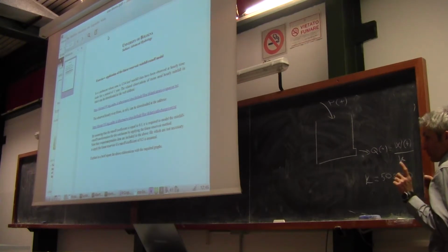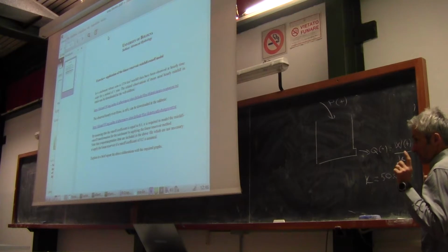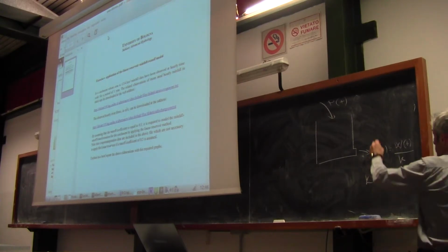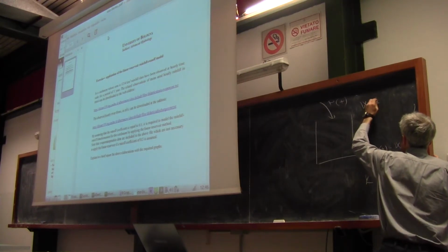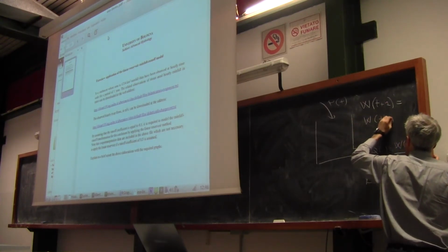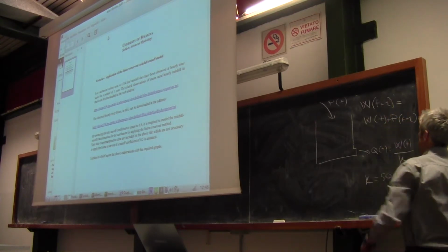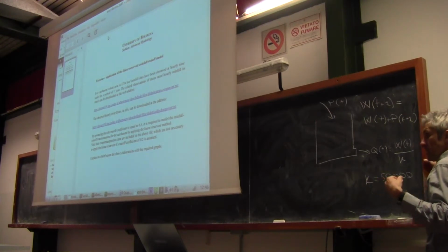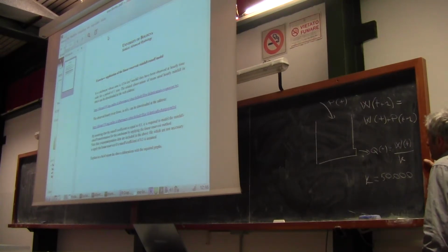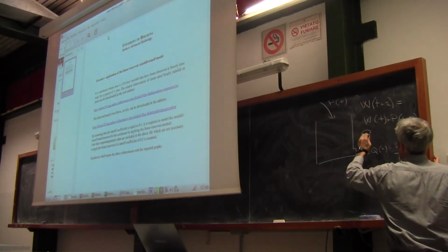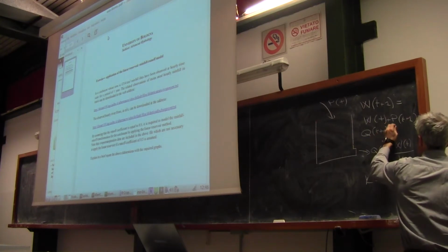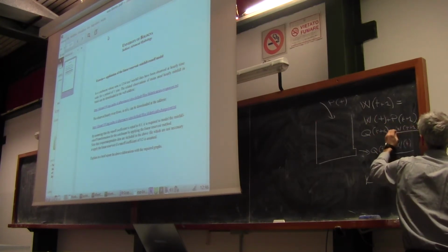And then what you need to do is, at each time step, so you need a cycle here, what you do is, basically, computing W. Let me say W_{t+1}, which is equal to W_t plus P_{t+1}. So you take the previous storage and you add rainfall. And then you compute Q_{t+1}, which is equal to W_{t+1} divided by K.